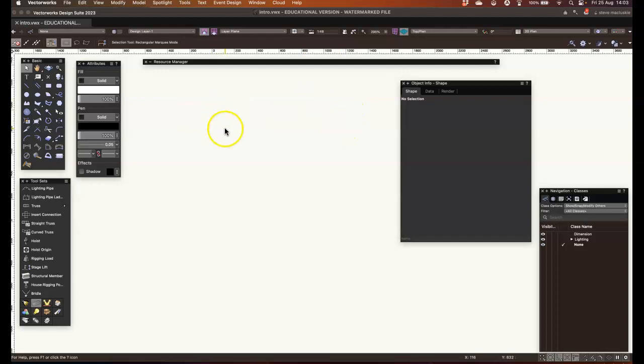We already set the units in an earlier screencast, but the one thing we haven't set is scale. Scale's an odd one. This design layer here is an infinite space, so scale is completely irrelevant at the moment. I could draw a line here which is 1 millimeter long and have it right across the screen, or I could draw a line here which is 1,000 kilometers long and just have it filling the screen. It doesn't matter at the moment. It's irrelevant until we place that drawing onto an actual sheet of paper. Then scale will become important.